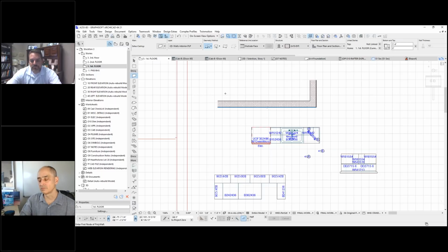Okay, so let me elaborate just a tiny bit, Chip. Since I have a master template, which we maintain and develop every year for the updated version, when you migrate a project or a template from one version to the next, ArchiCAD generally does a pretty good job of just making it look the way it did before. You do need to then switch your library from ArchiCAD 21 to 22, for example, and for the most part, everything will come across. It'll actually find the matching 22 part, and it'll be using that.